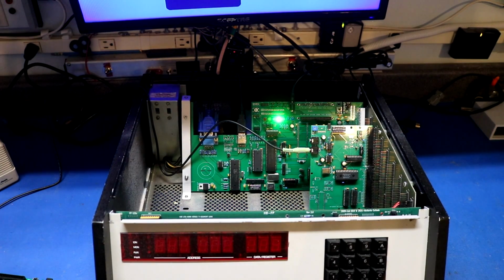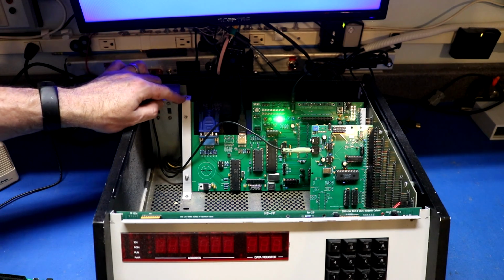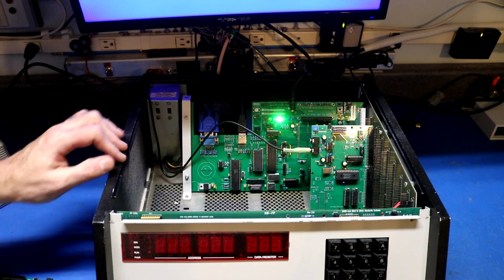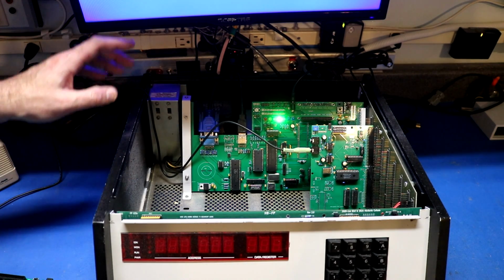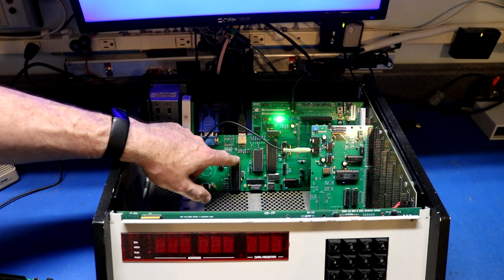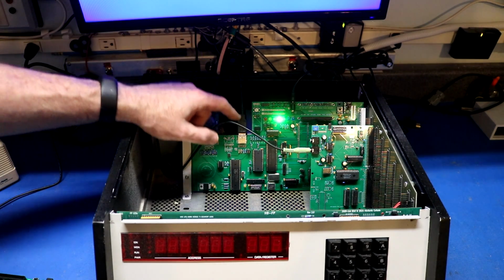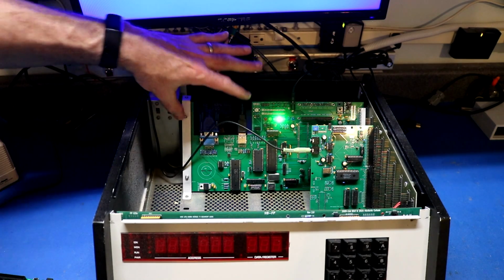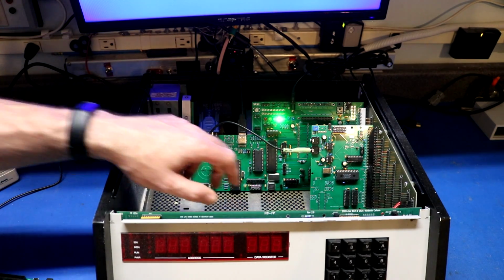Okay, let's go ahead and install this in my H8. So in the H8 we've got a few boards already. This back here is my dumb terminal board and VDIP USB board. It actually has a Propeller serial terminal, the Microsoft serial terminal. It's got a VGA output and a keyboard input, and this just implements a serial terminal. So it's got a 16550 UART on it.